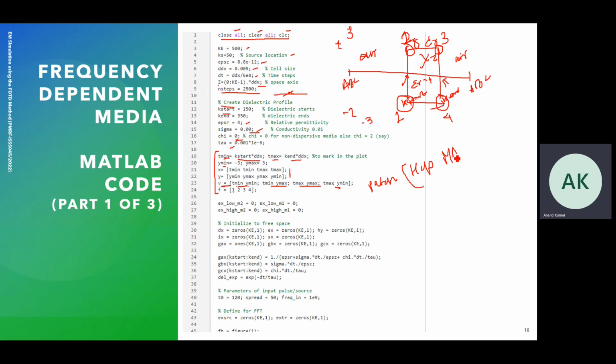This was one of the questions asked during the class, so refer to help of MATLAB to read more on the patch command. This patch function can take input in various ways. One of the ways is defining a matrix for vertices and a vector for faces, and you can also input variables directly.